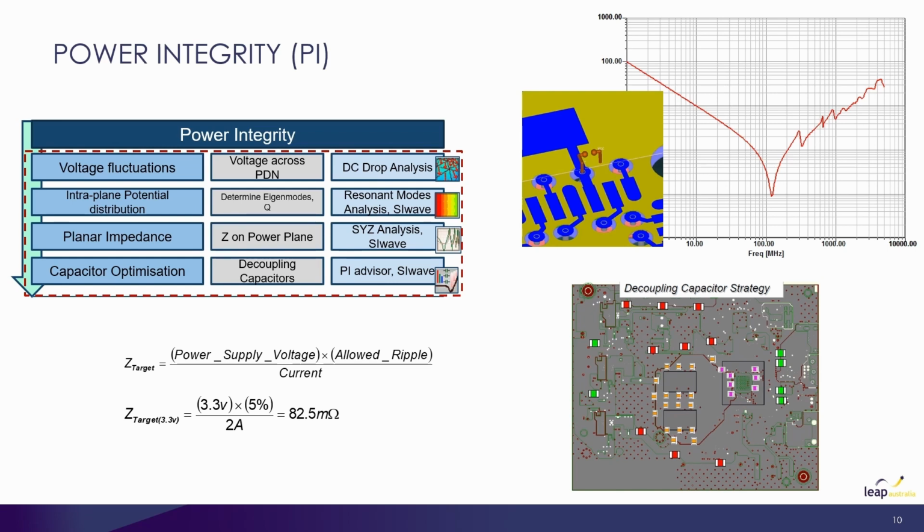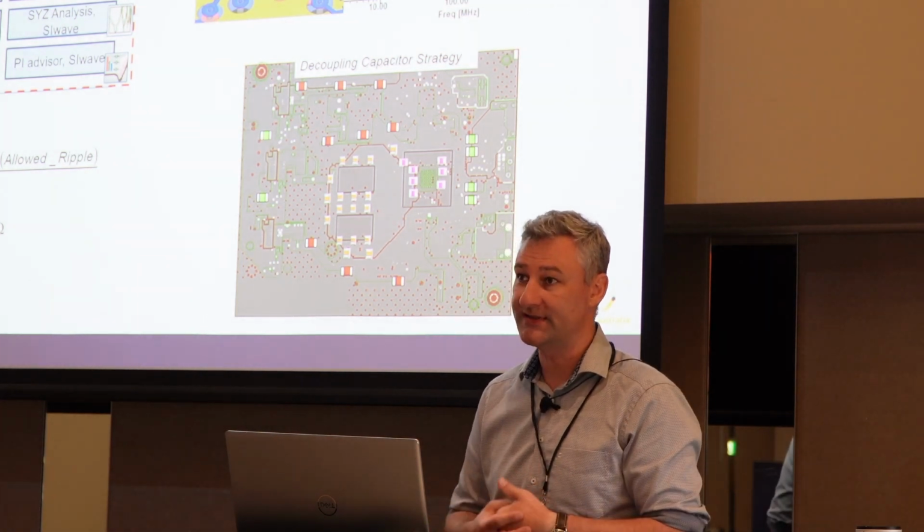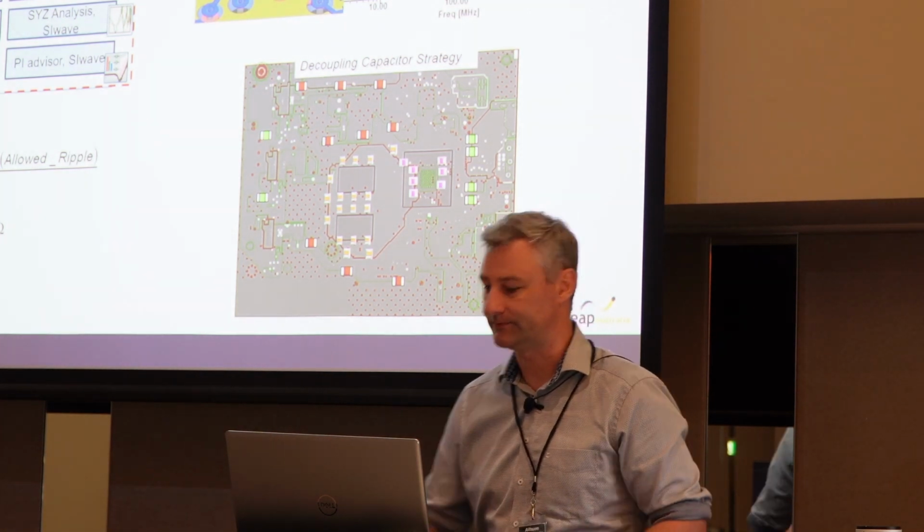Target impedance, I think everyone knows what it is, to try to fulfill certain targets. In the end, we use that target impedance, or the tool uses it. If you want to, for example, do a decoupling optimization with many decoupling capacitors, you can bring them in and run it, and then the tool will find out the best decoupling strategies for your board.